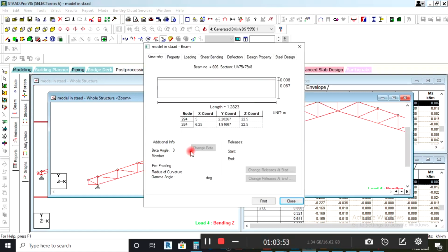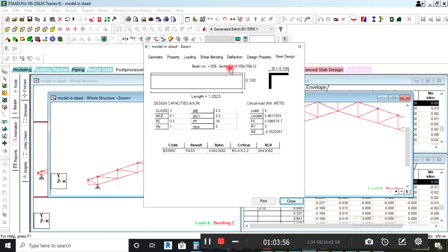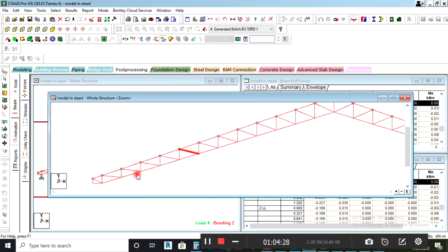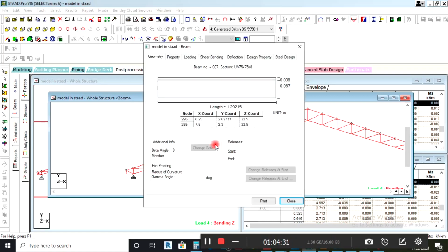So that means when we're detailing our design in AutoCAD, our struts here will be 100. We'll specify our truss. Those are our vertical and diagonal chords to be 100 by 100 by 12. Let's keep checking, but we hope that nothing is more than that.